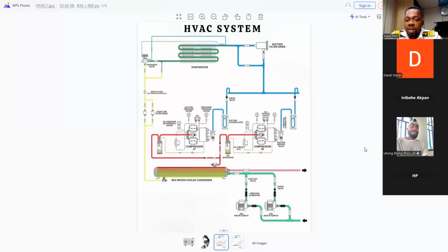All right. If you say that it's icing up at the discharge side, what is your discharge pressure and suction pressure? It could be that the system is low on refrigerant. Also you need to check around to see if you see traces of oil where you have your filter dryer and where you have joints, because that reefer is also fitted with an oil separator. Where you have those connectors, check if you see traces of oil. That means the system is slowly leaking out.